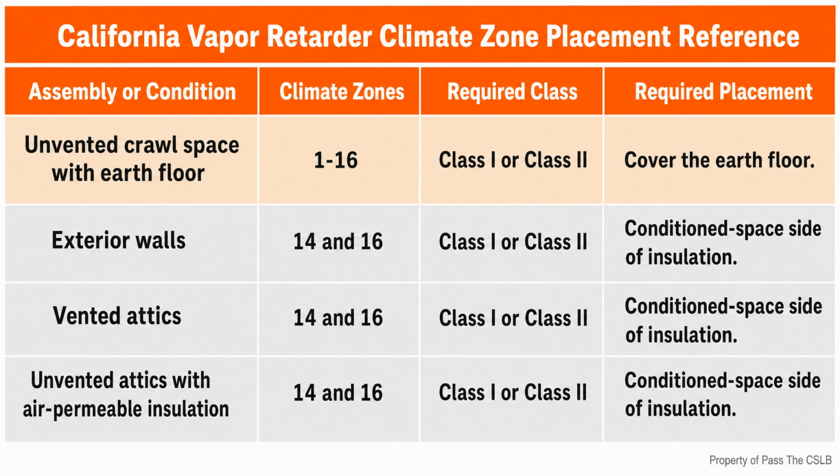At a slab on grade, the moisture control sequence is easy to remember if I stop picturing concrete as completely solid. Concrete contains pores that can draw liquid moisture. The verified California green building requirement uses a capillary break beneath a slab that requires a vapor retarder. The capillary break may be a 4-inch base of clean aggregate that is 1/2 inch or larger. The vapor retarder is placed above that aggregate in direct contact with the concrete.